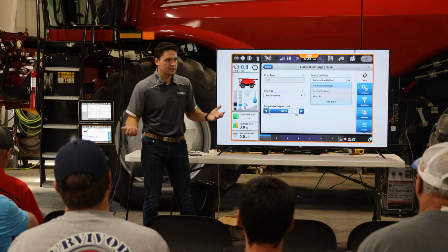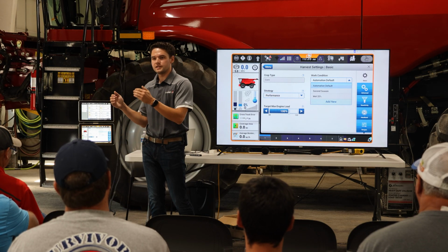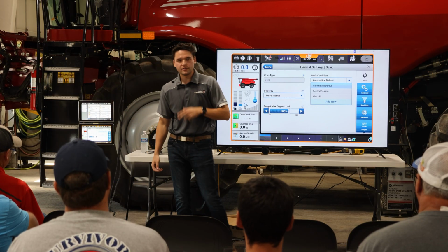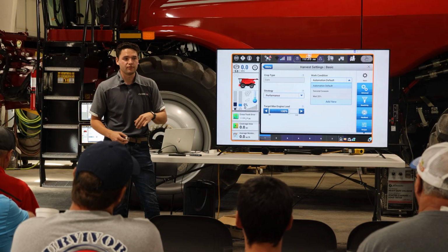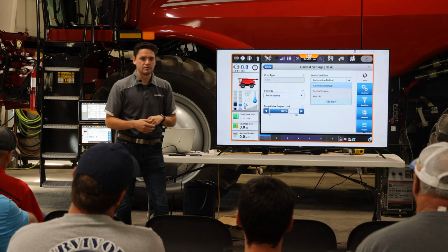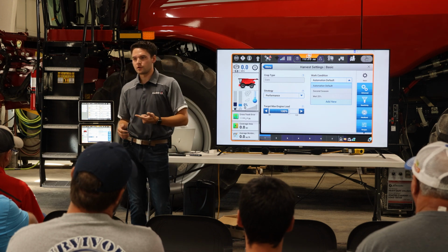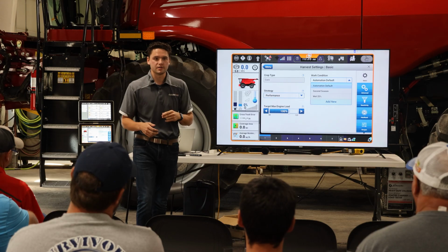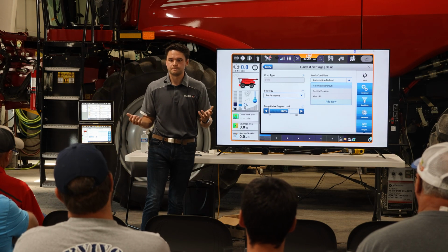The main benefit of work conditions is once you find what works well for that current harvesting condition of that crop type, you can go ahead and save it. That way, every time you return to that general baseline, all you do is select that, and then you don't have to find your sensitivities, ranges, and harvesting settings again. You have an original set point to go to. So we could have one for dry corn, one for high moisture corn, one for different cob types of corn, and so on. That way we don't have to have multiple harvesting conditions set up.